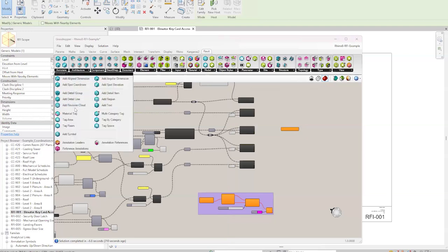So there are some dimensions. Dimensions are a little tough to do programmatically, right? Because Revit's requiring a specific face or a point. So if you're going to do that via scripting, you're going to really have to have either a lot of the same thing or a very good way of handling all the outliers. But you can do dimensions and things like that.